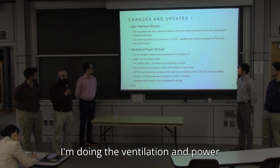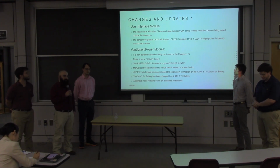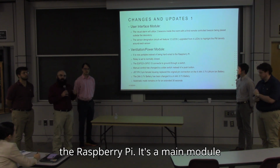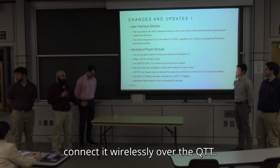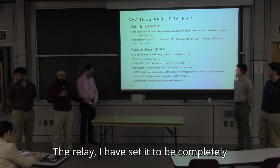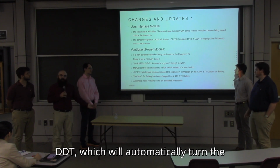I'm doing the ventilation and power module. The ventilation unit, the initial design was going to be hardwired to Raspberry Pi. Instead, I made a module where you're able to move around the room and connect it wirelessly over MQTT. The relay I set to be normally closed in case I lose connection to MQTT, which will automatically turn the fan on.